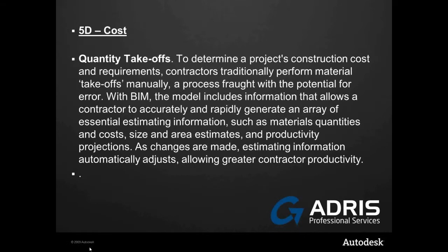So that's 4D. 5D is cost estimation. So with this, we have a BIM model that includes information that allows a contractor or anyone to accurately and rapidly generate an array of essential estimating information such as materials, quantities, costs, size, area, etc. So in real time, this is a means of assigning data and extracting materials, costs, size, area, and this data automatically adjusts as the model is progressing.